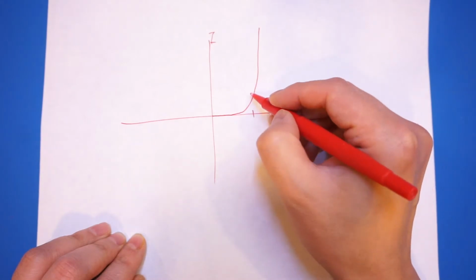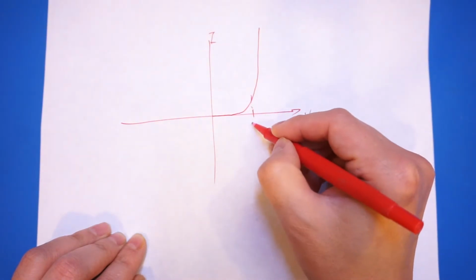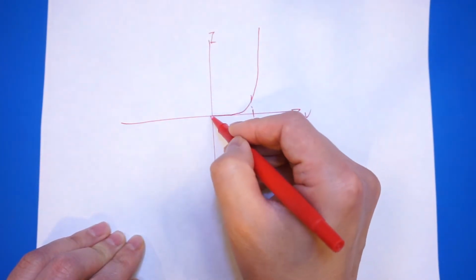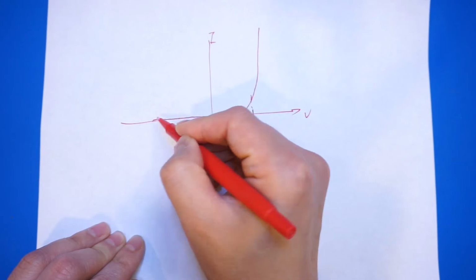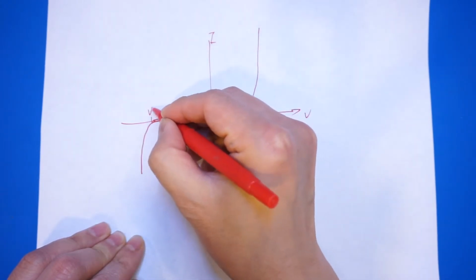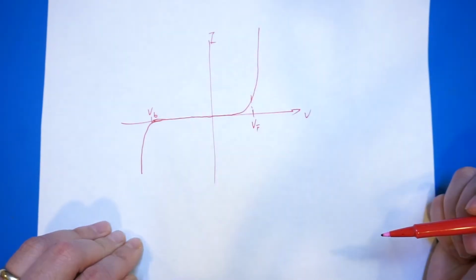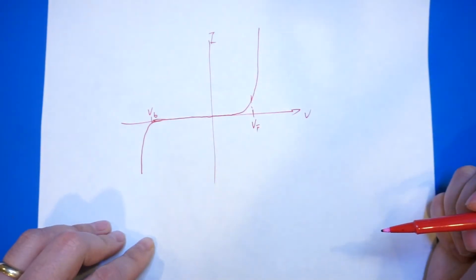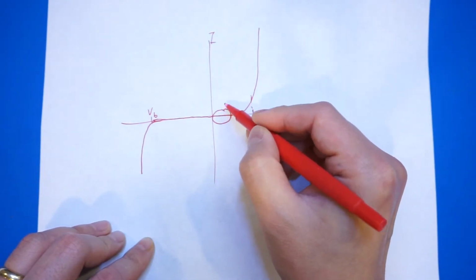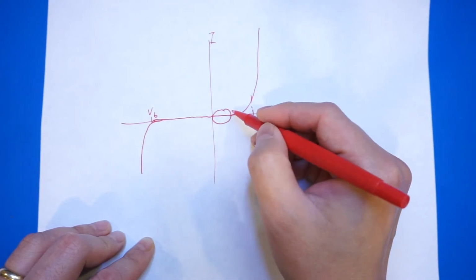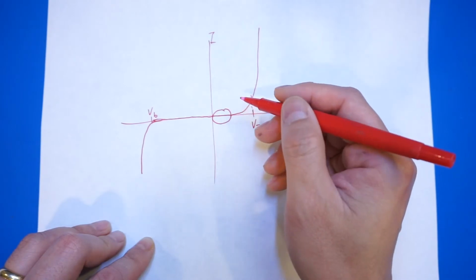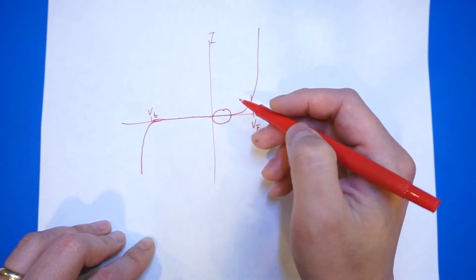After your voltage exceeds a certain level, let's say a VF, that's your forward voltage drop. And in the reverse region, again, you won't see any significant current until you reach a point where the voltage is the breakdown voltage. So here's a VB. That is the curve we are all familiar with. So now the question is, what happens in this region when the voltage is extremely small? Can we measure anything? That's the question asked by the viewer, which we will demonstrate in this video.